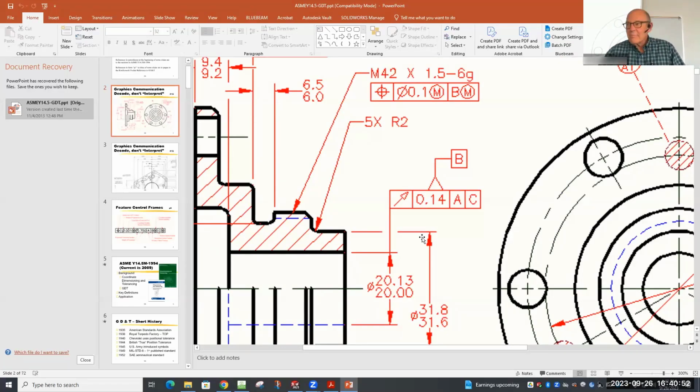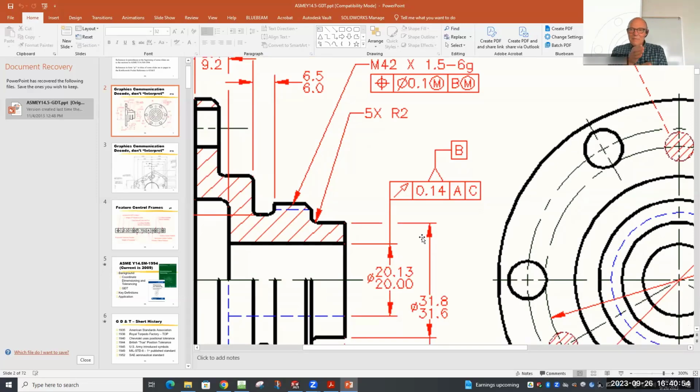If you've ever ridden a bicycle where the front wheel was a little bit warped, a little bit potato chip, and you're driving and it kind of does this and you put the brakes on and they do that, you're experiencing excessive runout. And runout just means the extent to which that wheel moves back and forth as it's turning. Now you can get runout on something like this as well. If this is spinning and I put a dial indicator right here, and as it's spinning the needle goes back and forth, that means this is now not symmetrical about its axis of rotation. So that's what runout is.